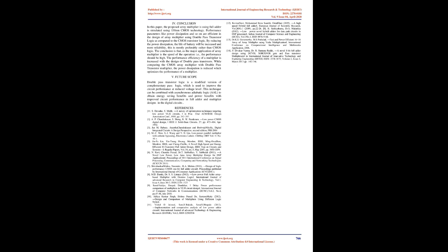Double-pass transistor logic is a modified version of complementary pass logic, which is used to improve the circuit performance at reduced voltage level. This technique can be combined with asynchronous adiabatic logic, AAL, to obtain energy-saving benefits and power benefits with improved circuit performance in full adder and multiplier designs in digital circuits.